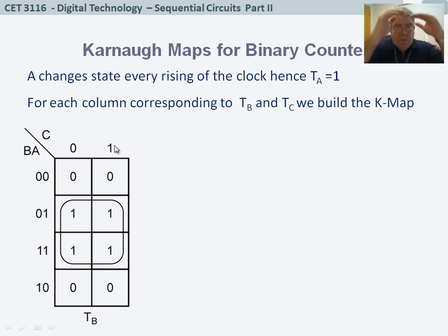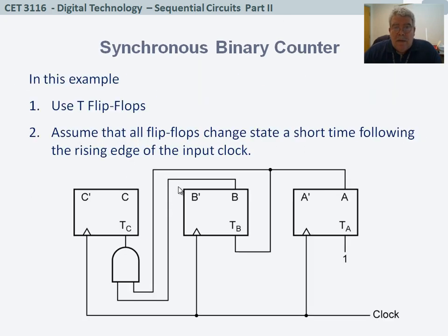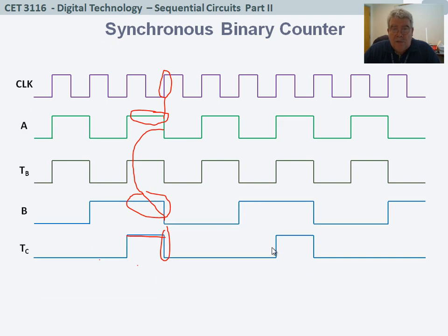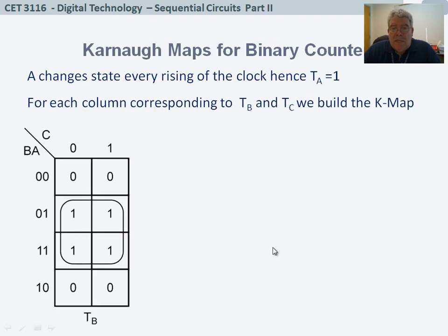If we put that in a table, that would be the table for the present state. Remember, the T value will depend not only on that particular bit, but may depend on the other bits. For instance, it's clear here that TC does not depend on C, but depends on B and on A. So they all are part of the factors that may possibly change.